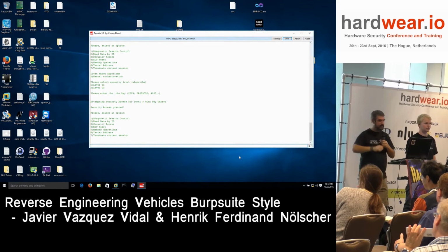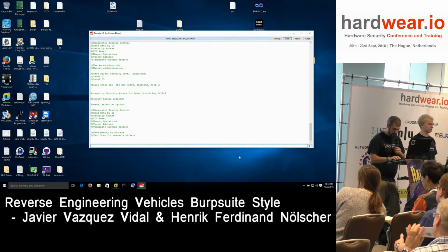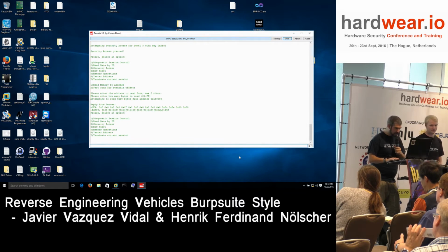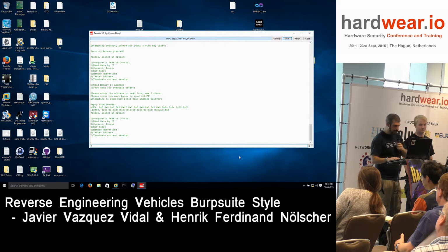So now we're in the ECU. If we want to read memory, for example, let's read memory by address. Let's start from 0x0000 and read 10 bytes. And there you go, there's a dump of the memory from the ECU. That's the normal way. You know the algorithm, you know all the stuff. So let's terminate the session.